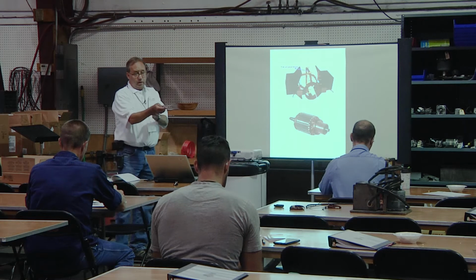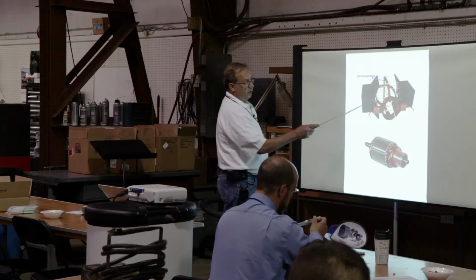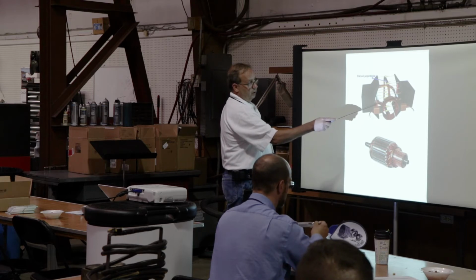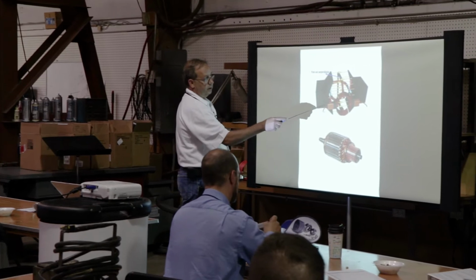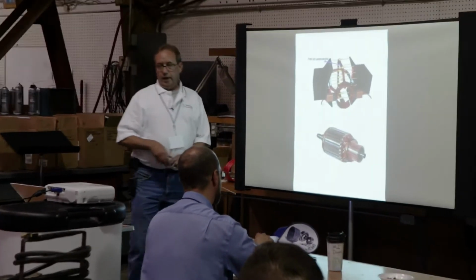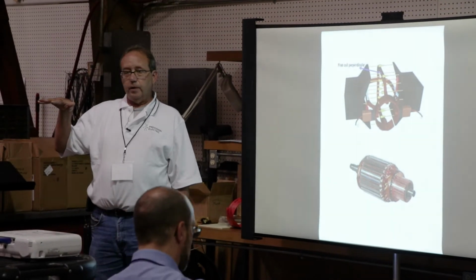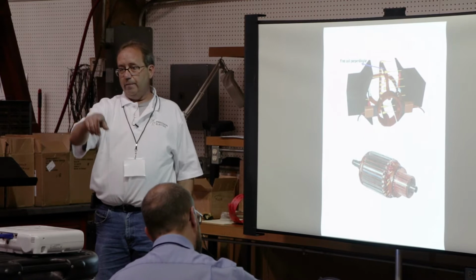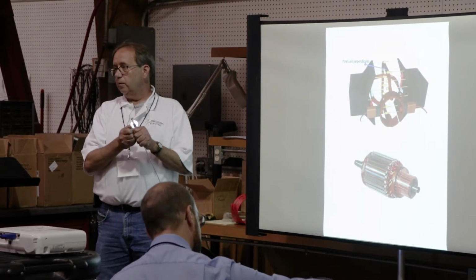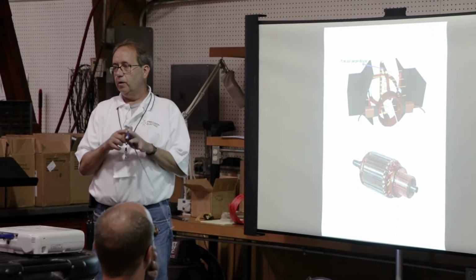and we're going back to our induction theory back here, is we're seeing that this coil here that's perpendicular to the pole pieces, as it's sitting there in a moment of time, it's right in the middle of that field, right? So if you hold that magnet in the middle of that coil, there's no voltage or current induced into it at all.